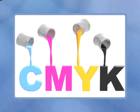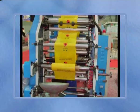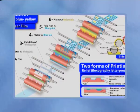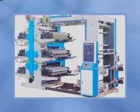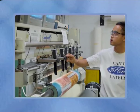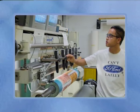Mounting. For every color to be printed, usually cyan, magenta, yellow and black, a plate is made and eventually put on a cylinder which is placed in the printing press. To ensure an accurate picture is made, mounting marks are made on the flexographic plates. Then the image transferred from each plate has to fit exactly with the images transferred from the other colors. Highly accurate and specific machinery is made for mounting these plates on the printing cylinders.